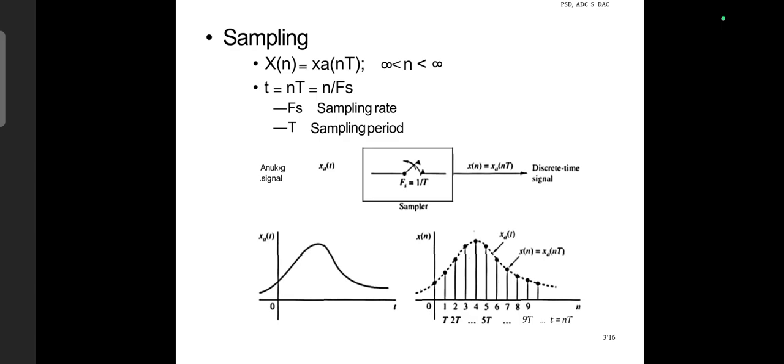Look at the waveform shown on this slide. The continuous analog waveform is represented first. The sampler takes measurements at regular intervals. Each measurement gives us one sample of the original signal. If we take more samples per second, we obtain a more detailed representation of the original waveform.